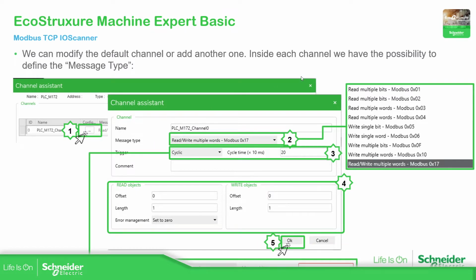If you add a channel, you have the possibility to configure it. In the configuration for each channel, you need to specify the message type that is related to the Modbus function, as you can see over here, of the functions that are available on the IO scanner. Then you should be able to select the trigger, because you can specify it to be periodic. You have a cycle and you can define the cycle, or you can define a variable memory bit in order to trigger the execution of sending or receiving information to the other side.